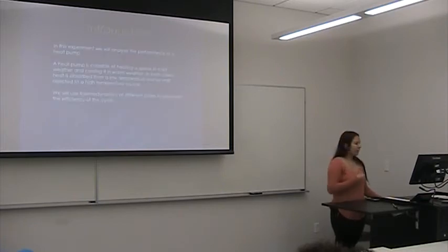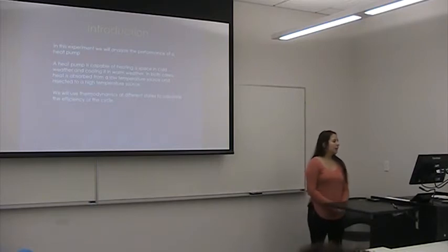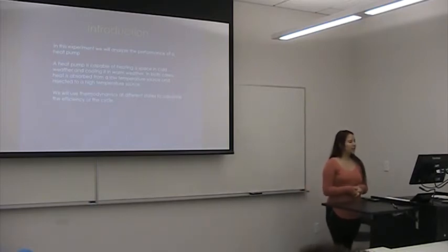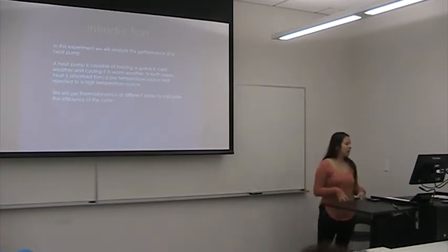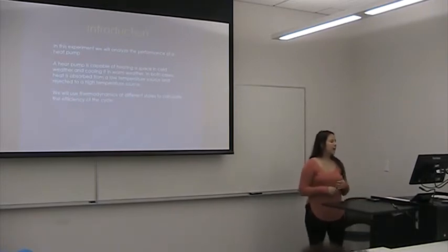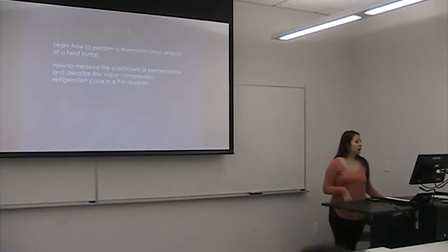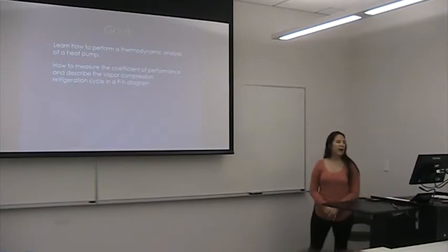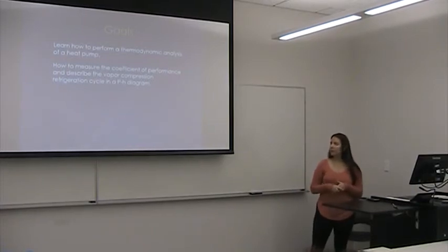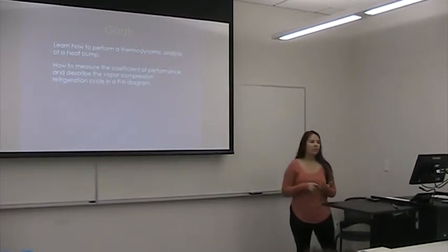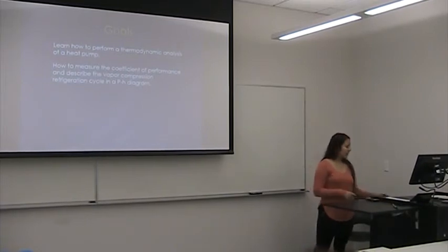The introduction. In this experiment, we'll analyze the performance of the heat pump. A heat pump is capable of heating a space in cold weather and cooling it in warm weather. In both cases, heat is absorbed at low temperatures and it is released at high temperatures. And we will use thermodynamics at different states to calculate the efficiency of the cycle. The goal is to learn how to perform a thermodynamic analysis of a heat pump and how to measure the coefficient of performance, which is the COP, and describe the pH and the TS diagrams.